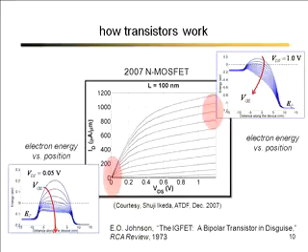We call this the saturation regime, saturation in quotes, because the drain voltage is still having a small effect because the electric fields are penetrating over here and affecting the height of this potential barrier. But the current is more or less saturated. Okay. So the point here is that a MOSFET is a barrier-controlled device. The gate just lowers and raises the barrier between the source and the channel, and that controls the current flow.